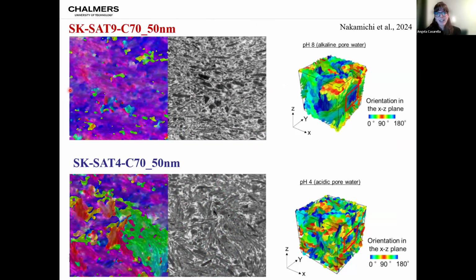alkaline conditions, this kind of aligned behavior is also confirmed by some of the numerical research in coarse-grained molecular dynamics carried out at Imperial College London by Nakamichi et al. And so this could allow us to make the link that I was mentioning before between the clay micromechanics and the particle-scale clay mechanism that we have already been seeing in coarse-grained molecular dynamics in granular materials, and can eventually be reproduced for fine-grained soils in this case.